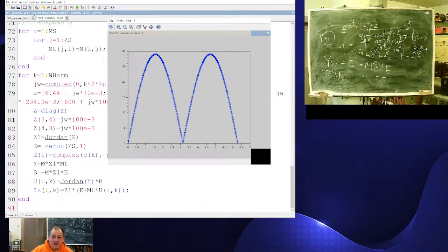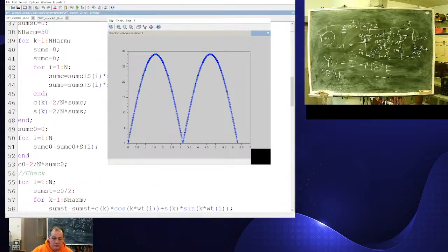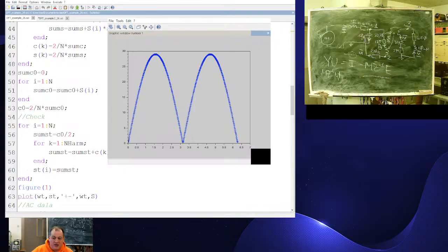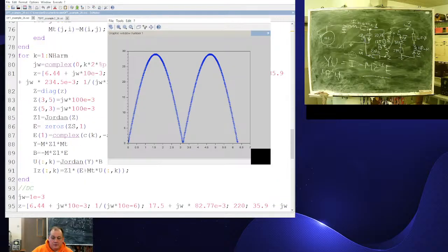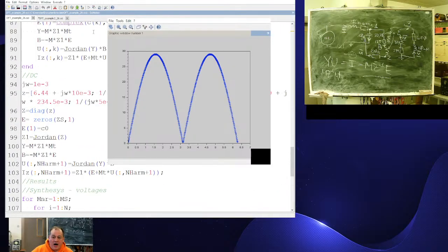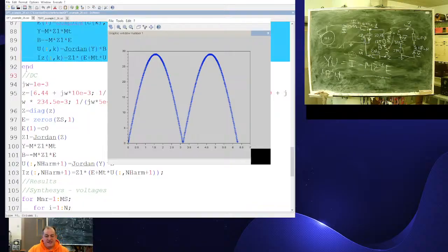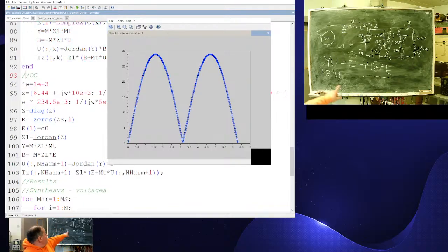And here, if I would follow good practice, what should I do to solve DC? I will need to create DC schematics. Exclude all capacitors, because capacitor resistance is infinite in DC mode, and short circuit all coils, because inductance is 0 at DC.